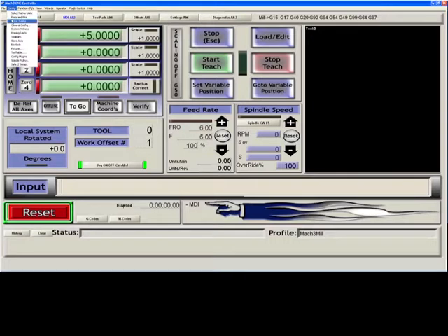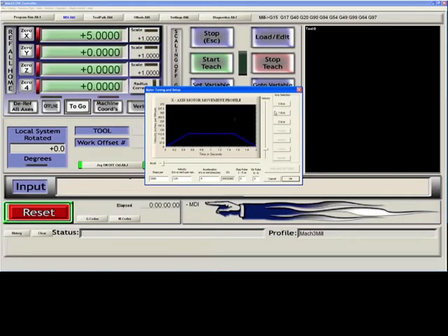And if we go up here and bring up motor tuning, you can see that for each axis there is a steps per. This needs to be set to the number of steps the system needs to send out to move your axes that amount, 1 millimeter or 1 inch, depending on the selection that you have selected for the system. The acceleration and the velocity you should set to a comfortable level prior to doing anything, and hit Save Axes for each axis. You can then adjust your steps per inch to make the system accurate.